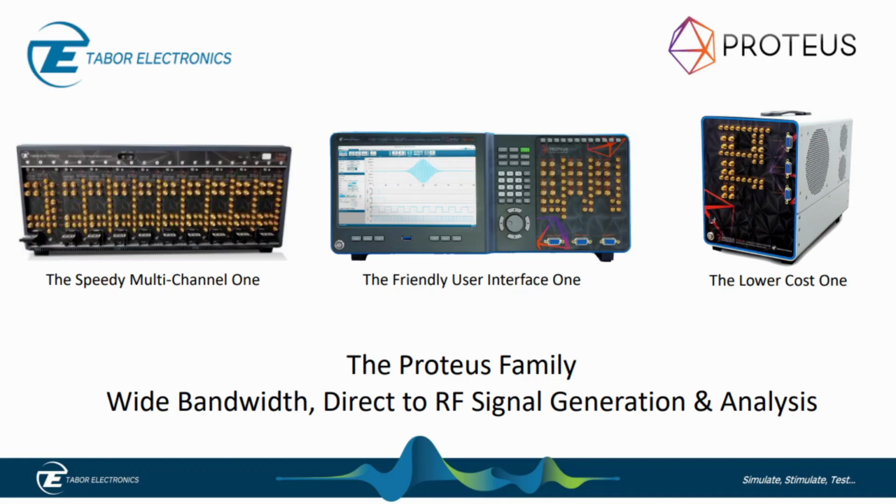And that's not only good for MIMO. If you're doing angle of arrival, for example, in electronic warfare systems, 4 channels you could feed to a radar warning receiver, and you could create different scenarios of angle of arrival with different threat models. If you just need it on a bench, you can have either 12 channels of arbitrary waveform generation, or you can have 8 channels of arbitrary waveform generation and 4 channels of digitization, all in the same unit,